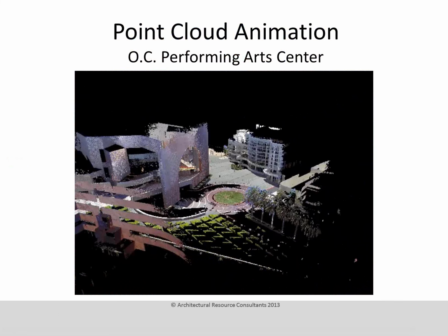Now take a look at some methods that engineers are using this data for. One of the biggest things that we see engineers use this for is above ceiling plenum scanning and modeling. And this is probably one of the most difficult things that we do, primarily because of access and getting the scanner to see everything that needs to be documented. We have to get the scanner up into the ceiling, so we either have to pop ceiling tiles or find access panels. The more we can get the ceiling open, the better.